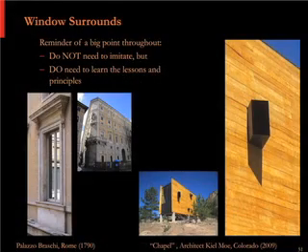And then for any water that leaks through the window or any condensate on the window, there's an internal trough. So you see that as kind of the curved piece just slightly below, or maybe an inch below the window in the photo at left. And that's also in that little section sketch in the center. A curved marble trough, it's drilled through, there's a lead pipe inserted through, and it's actually soldered to the marble. So two drainage troughs. So then if you look at the photo at the lower right, you'll notice on the facade there's two little dots, and those are the weep holes where both of those systems drain.